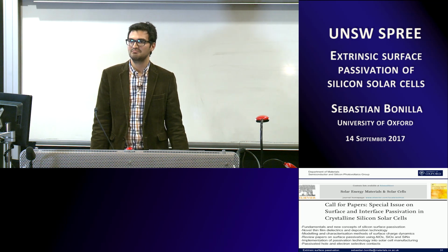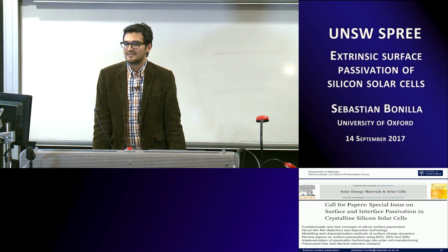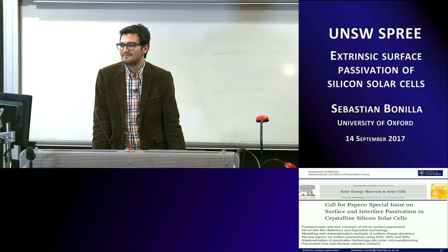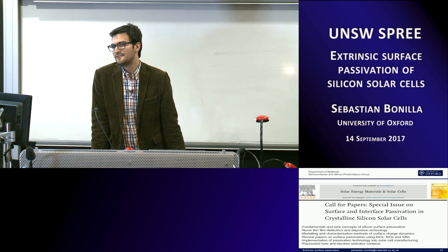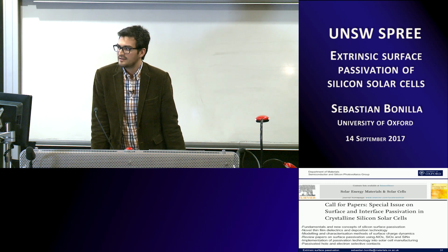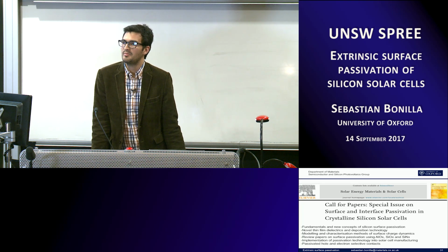whenever possible, people should quote all of them. In that paper, they give guidelines as to which metric you should give under certain conditions. If you follow the conditions that they suggest, then whenever you have a heavily charged dielectric, you use the J naught, and whenever you don't, you use surface recombination velocity. But having said that, I think there may be occasions where that doesn't hold.